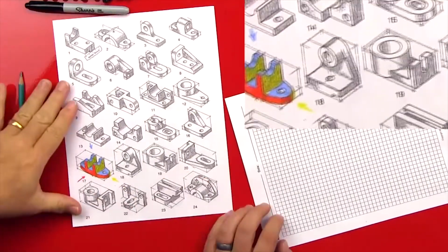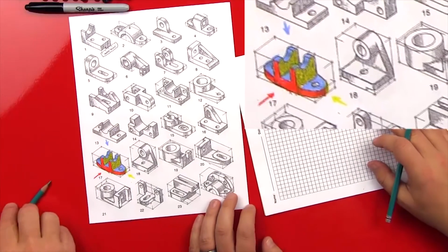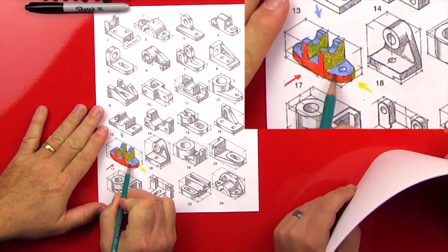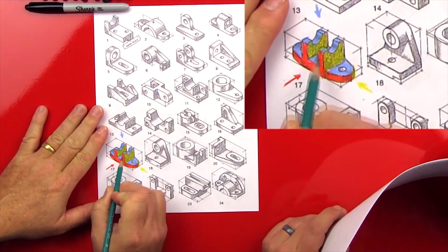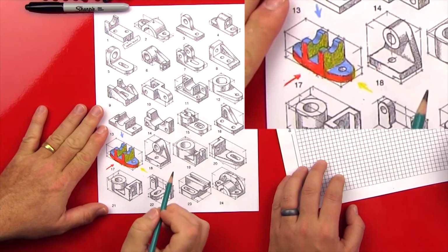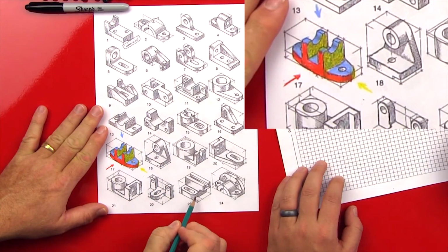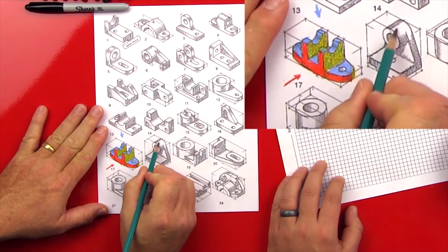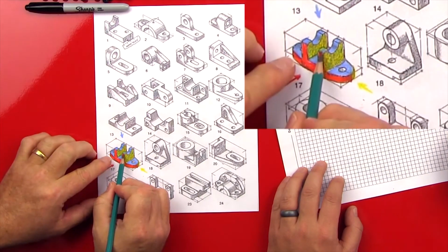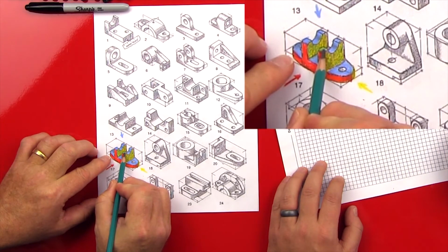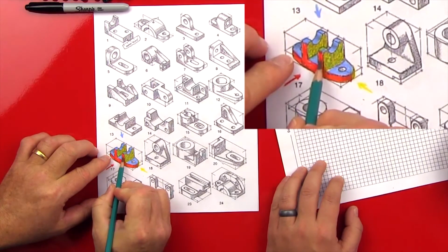All right. Now, maybe one thing that we should talk about before you start drawing is there's these little chicken feet or hash marks all the way around here. There's some right there. Does that mean there's a radius? Yeah, so you see this kind of stuff over and over again. So here there's little edge marks and they're trying to show a really small radius that blends from a flat surface to a flat surface.